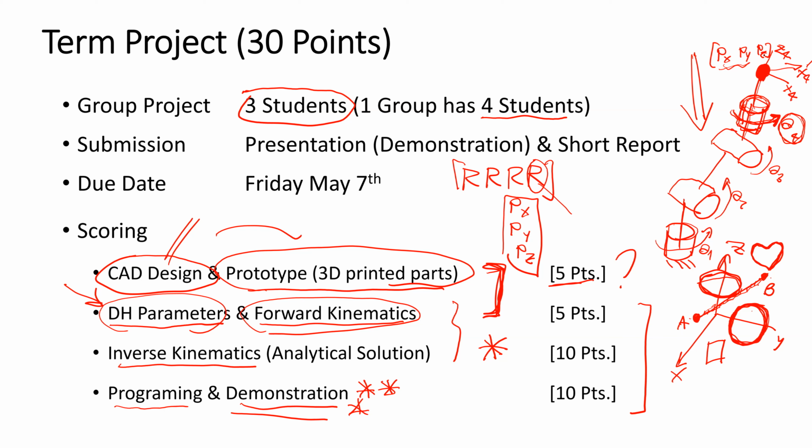It means that you have only 3 degrees of freedom to drive the robot to the desired position. And the joint 4 just change the orientation at the end effector. You may say that the robot doesn't have the redundancy. If we want to go to this XYZ position, we can go to the position in maybe the limited way, because we cannot have the redundancy in the robot.